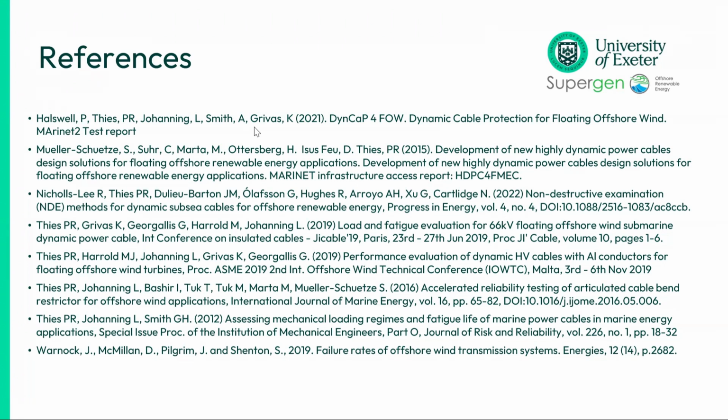It is, and that is one of the challenges. I think it is very site specific and also floating platform specific. All the different platforms have different constraints, which is why I talked a little bit about the coupled modeling as well. Things like the excursion of the platform will determine what the cable has to survive. So if you fix your cable design, you have to make a mooring design that accommodates it. But primarily you'd make the mooring design to stabilize the platform, so you have competing design objectives a lot of the time.